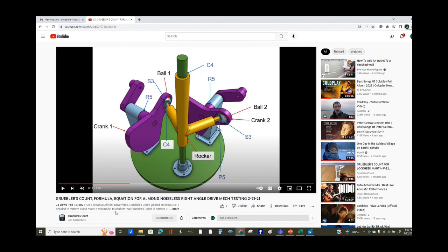Yep. Thank you. Yeah, no problem. And back to the example about the ball table with the 2 THK rails. I used to have to troubleshoot those when they were binding, and I almost always found out that the planar surfaces the rails mounted to weren't parallel to each other, and they almost always bound up.